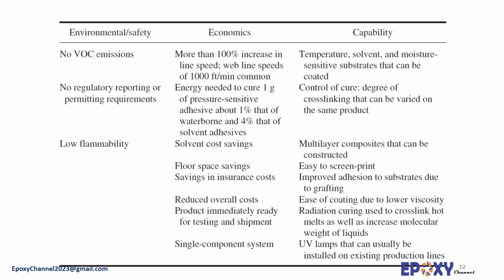Benefits of radiation cured epoxy systems have been presented here. Radiation curing of epoxy systems significantly reduces the cure times needed for conventional epoxies, which is crucial for adhesives. In adhesive applications, radiation curing provides high glass transition temperature, low shrinkage during the cure, no volatile emissions, excellent shelf life, and relatively low residual stresses. Moreover, for adhesive applications, the absence of heat, water, or solvent in these coatings is a merit. Other benefits of the radiation curable adhesives have been tabulated in this table.